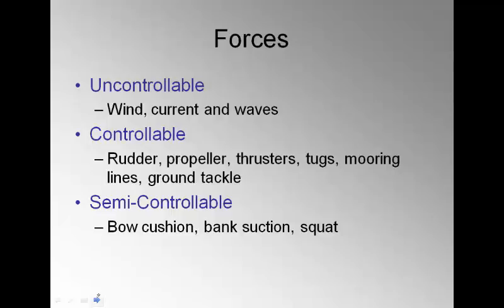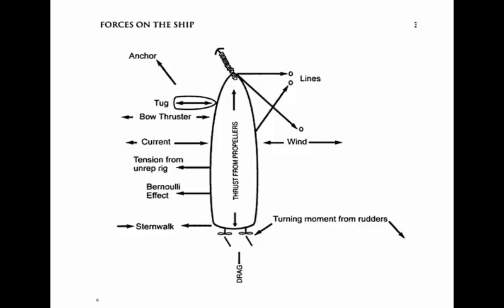Same with bank suction and squat. And we'll talk about these things a little bit later on in the lecture. But to sum it up, if I am close to a bank and I'm proceeding at a certain speed, I'm going to have a certain amount of suction force that's going to want to pull me into the bank. Now the faster I go, the more of that suction force is going to happen on my hull. And the same thing is true of squat.